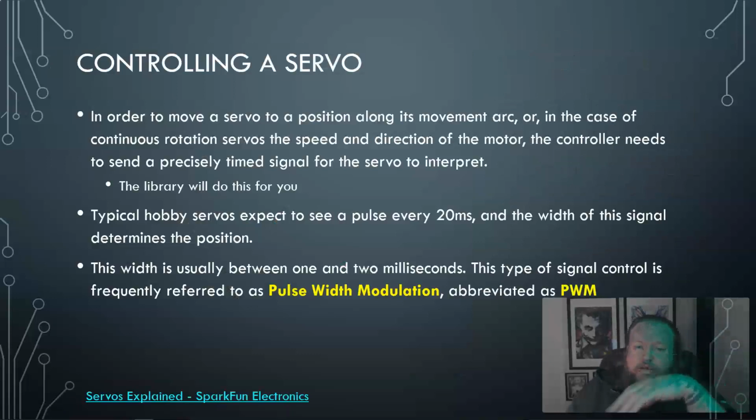Now, be aware that this is extra information on these slides. At a lower level, there's a lot more going on, like when you're sending signals at a specific rate for the other device to actually interpret what's happening. If you go further into electronics and more electrical engineering, then you can understand what's going on here. We'll be working in the libraries where some of this has already been handled for us. But the most important thing you need to be aware of is that data line: you have to connect it to a PWM pin. It needs a pulse width modulated signal coming in a specific way. And so you have to connect it to a PWM pin.